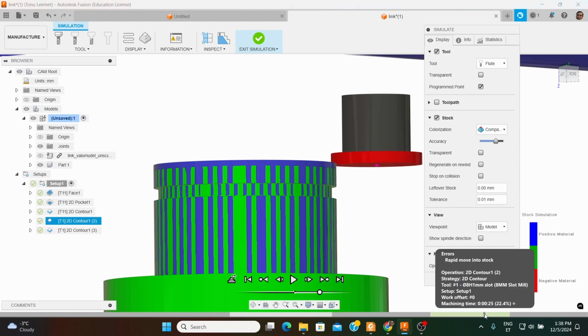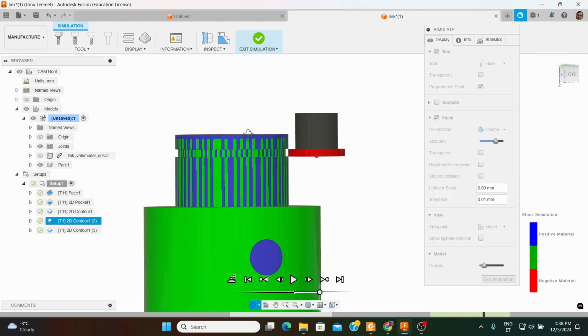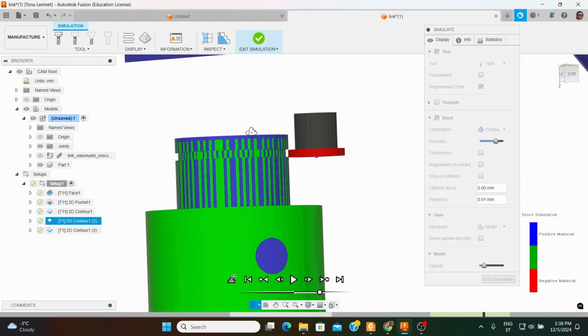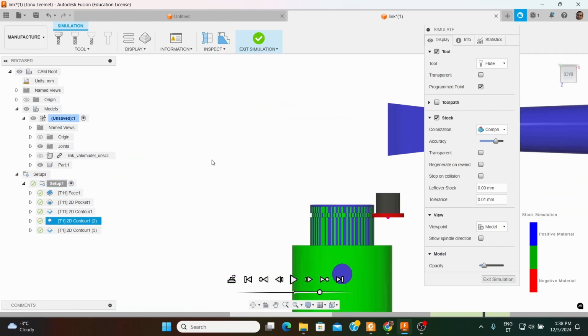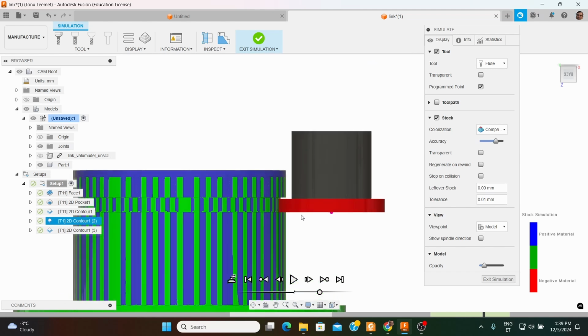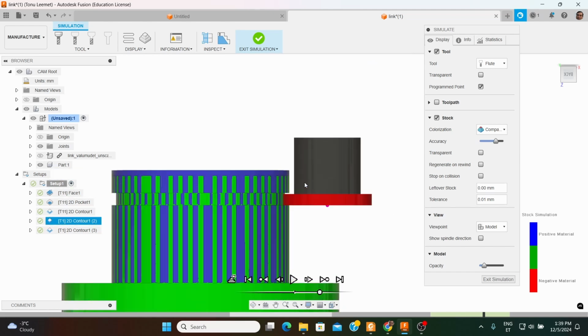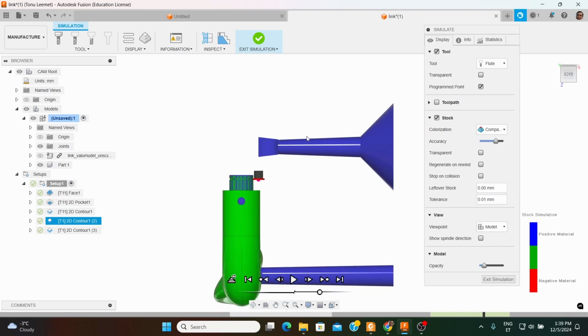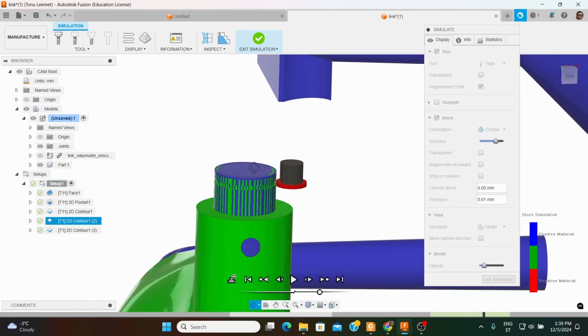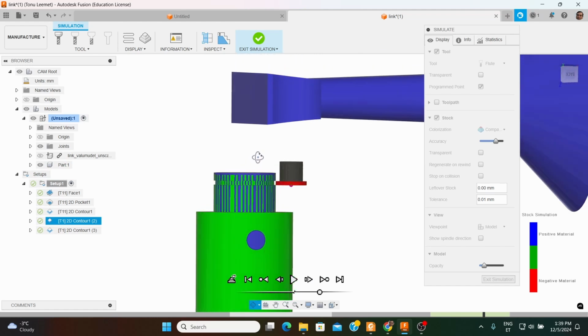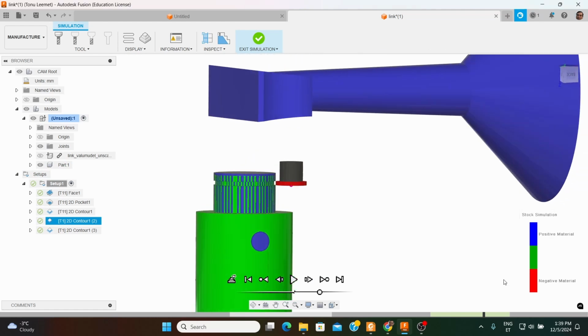And I'm not going to worry about this warning here, because quite clearly there is some mismatch between the understanding of the toolpath and our real situation, where we have actually cut off. The program is not able to take into account that this part has already fallen. We have free access to this part of our piece for machining. Let's leave it as it is for the time being.